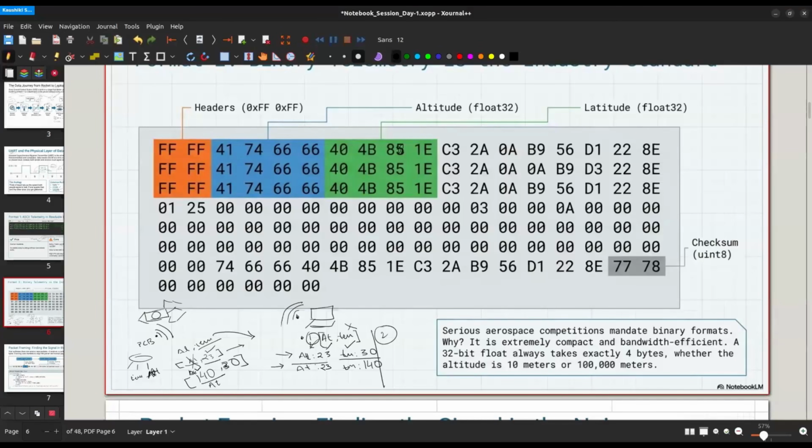So suddenly you will see that this is your altitude trying to go up, and suddenly it drops down, and this is the temperature that was going stable and then just increases at some point. It went up this high. And when you see this, it's really a fault from the GCS. You'll get confused. Even your team members will all get confused at what is happening. Why is the temperature showing 140 when it was supposed to be the altitude?